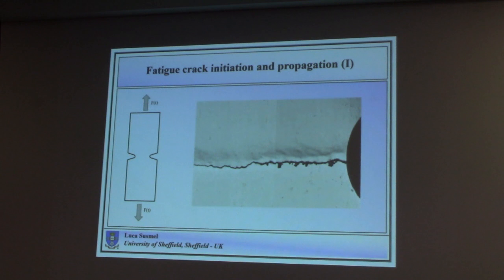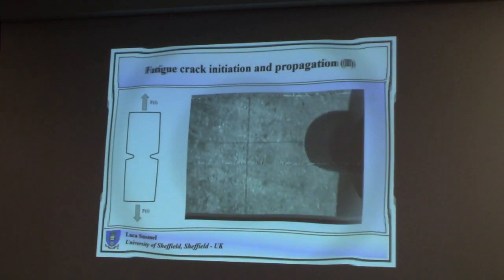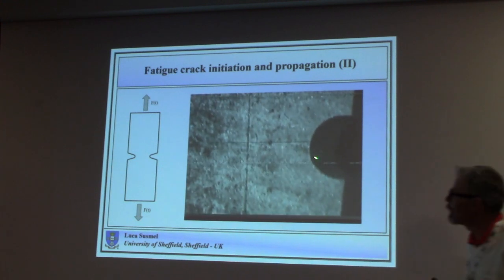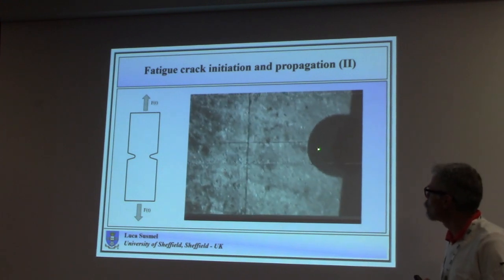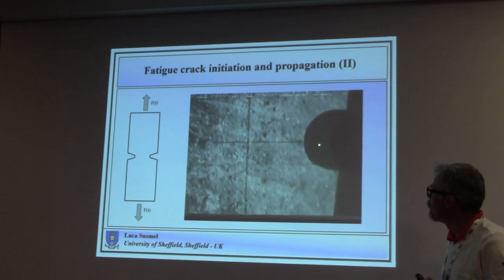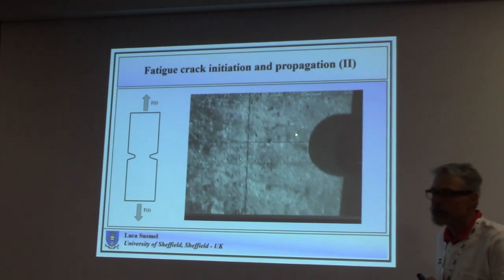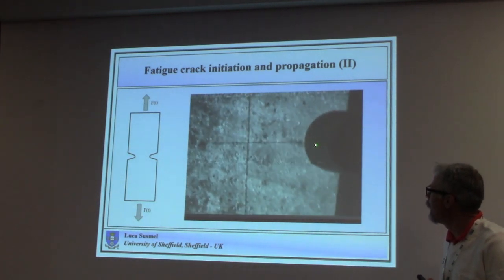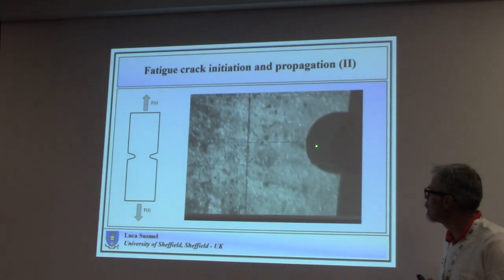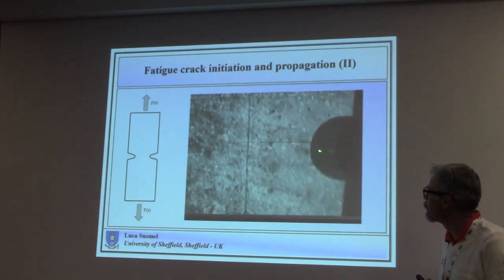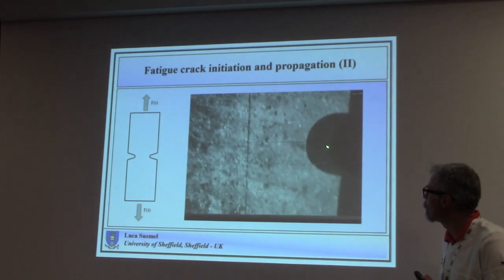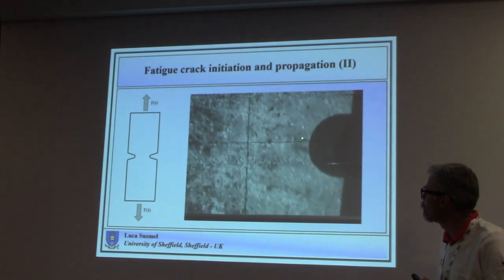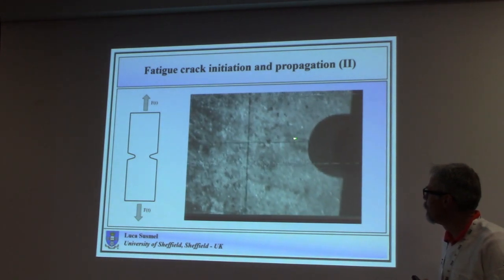So this is fatigue, but actually fatigue and propagation is a quite complex problem, because if we see the same problem from another angle, you'll see here at the midsection of the plate, a little white spot appearing initially, cycle by cycle. Here we have this white spot appearing, and after a little while, you see that that is the crack initiation point propagating toward the two surfaces. You can see here the part of the crack being already appearing. Now the crack is moving toward the surface, and now the crack is eventually on the surface.